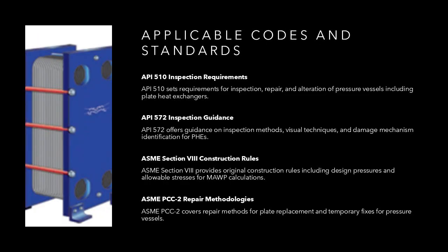This slide summarizes the primary codes and standards that form the technical basis for PHE inspection. API 510 establishes the requirements for inspection, rating, repair, and alteration of pressure vessels, including those of unconventional design such as plate heat exchangers. API 572 provides detailed guidance on inspection practices, visual examination techniques, and identification of damage mechanisms that are directly applicable to PHEs.